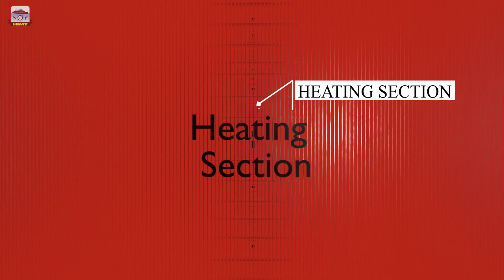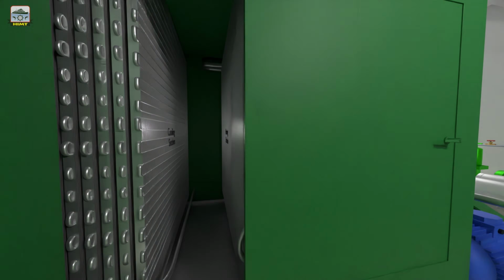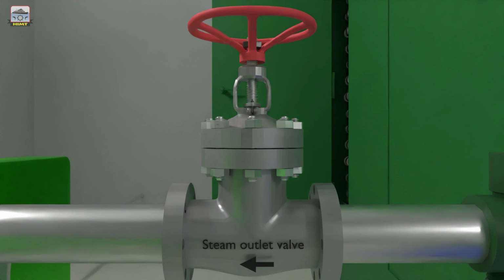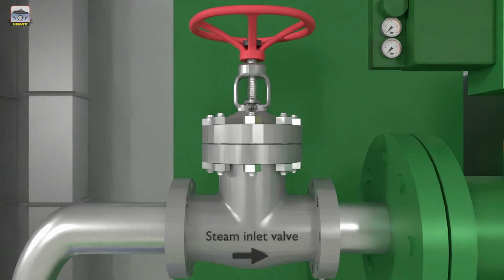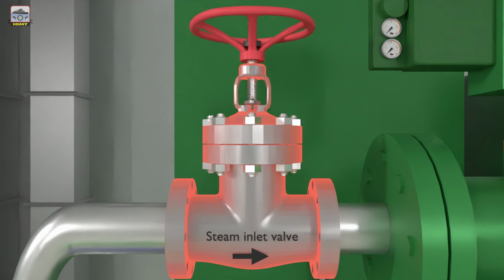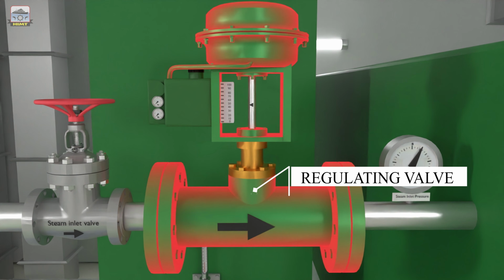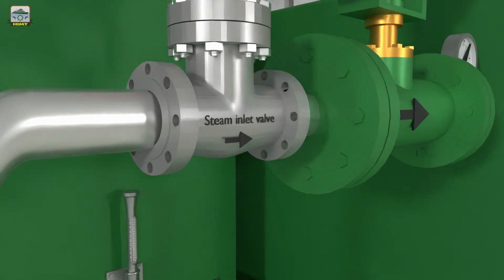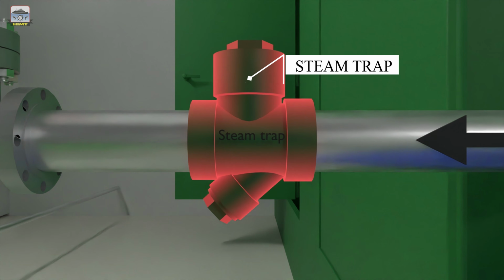The heating section is supplied with saturated steam of 4 bar pressure through a cross-fin coil. This section of the air handling unit is used when outside atmospheric temperature falls below 16 degrees Celsius. The heating coil is fitted with a manual valve for isolation of the heating coil at the steam outlet and inlet lines. An automatic diaphragm-operated regulating valve at the steam inlet line regulates the quantity of steam entering the heating coil to maintain constant the temperature of the air leaving the accommodation blower. A steam trap also is provided at the steam outlet line to optimize the usage of heat content of the steam in the heating coil.